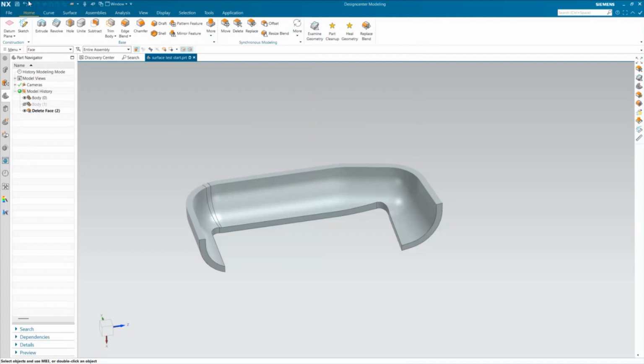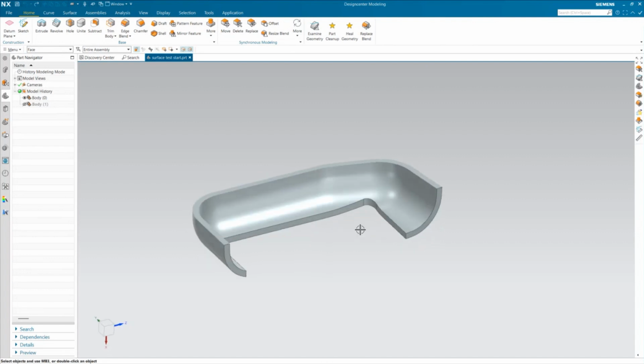So let me go back and take this all the way back to optimize face if we first open this up. Now you guys notice I had these icons up here. I added these icons. A simple way to add these icons, guys, is to be in the tab you want it to go into and come up to your search. If I, for example, said part cleanup, guys, and I came down and hit this, that's going to take me straight into my dialog.